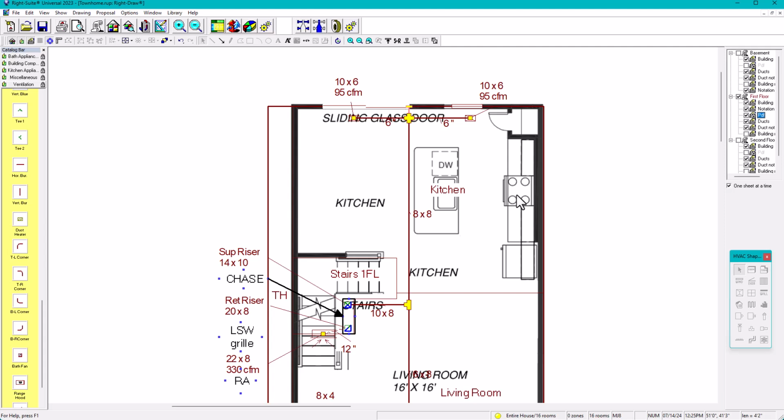We can do that in the next video. Honestly, I'm gonna make a next video about codes, and that would be the last video of my series. In that case, they will show you the CFM, because some range hoods have low, medium, high speed, and if that CFM is more than 400 CFM, you need makeup air, and we're gonna check on that code later.